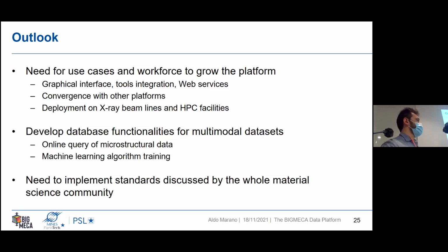But to avoid problems, that's one thing that we are working on. For now, the files are synchronized, so you can have problems with duplications, synchronization problems. But the idea would be to build the XDMF file only when you want to visualize it, for instance, from the information that is in the HDF5 file, which can be done easily from what we have developed. So that would be my answer. Focus on the HDF5.